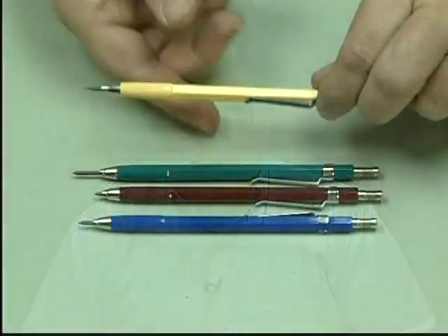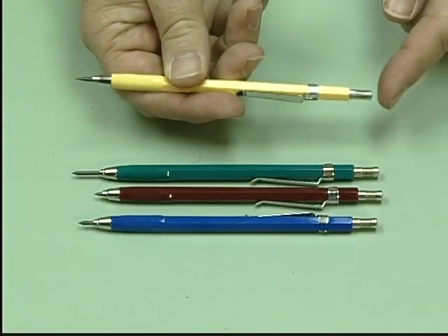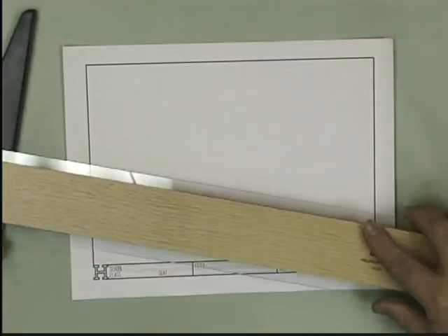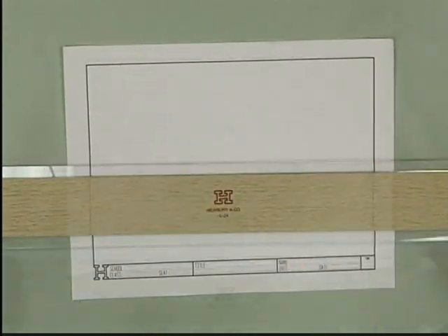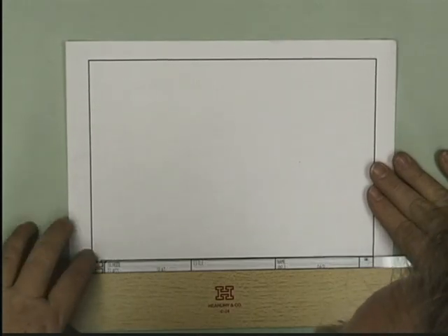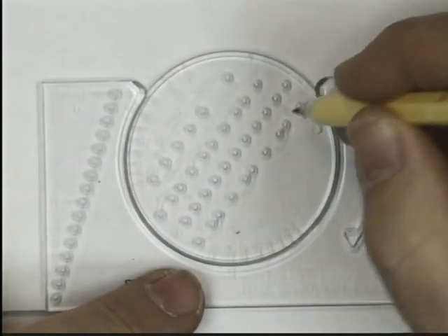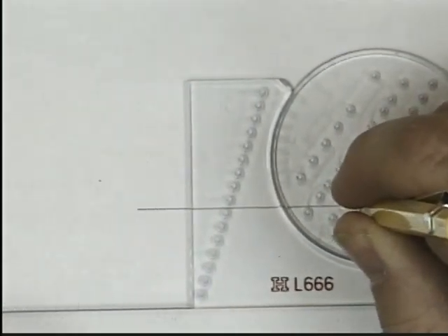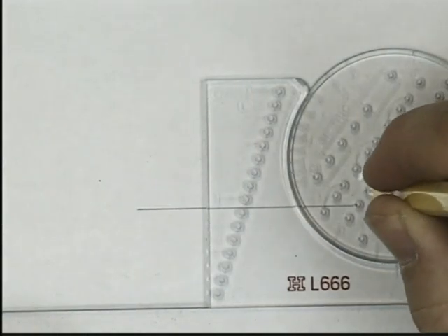In this brief introduction to the use of drawing instruments, you've taken a look at different kinds of pencils for making lines. We've made lines with triangles at different angles. We've used a T-square to make horizontal lines. We also used a T-square to align up the paper so that all the lines would be aligned with the border line of the paper, not the edge of the paper. You've also seen how to use a lettering guide to make equally spaced construction lines to add words or text to drawings. Well, this is just the beginning. In the next videotape, we'll explore more of the drawing instruments used for making engineering drawings.